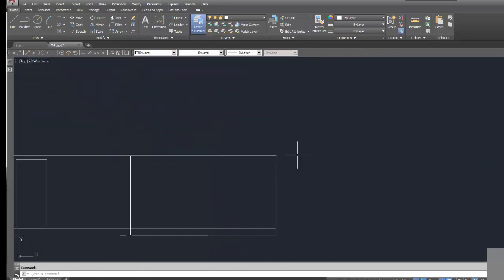draw another line segment on the right side and on the left, but then we'd have 3 lines there on the top. And I think that's a little bit messy. A cleaner way to do that is just to grab this line we've got here, and you'll see it's got these grips. Once you left click on the blue grip, it turns red, or it makes it what they call hot. And as I drag to the right, I see a dimension that's highlighted in blue, which lets me know that I can type a dimension in.